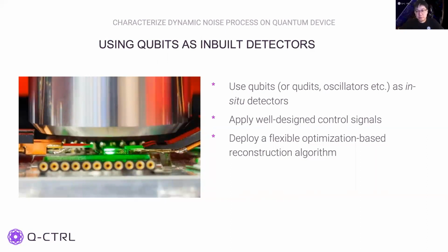A noise spectral density, which provides information about the noise strength as a function of frequency, is a useful characterization tool. Often the origin of a noise can be recognized through spectrum features or the power law a noise power spectrum has. Furthermore, the noise power spectrum can be used to engineer controls that are robust to the noise in the relevant frequency windows. Characterizing a noise spectrum can be practically difficult